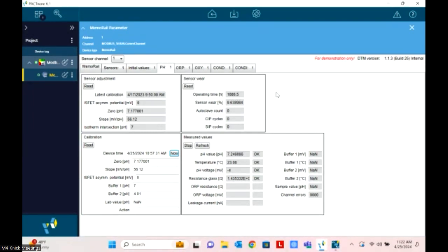Now, obviously, we can start scheduling PMs based off, say, wear percentage. Now we know, as opposed to sending our technicians or our operators out on maybe every 2 weeks or a monthly basis to just check those electrodes and clean and calibrate them, well, why wouldn't we utilize percent wear to give us an insight as to, is it time to clean that sensor and recalibrate that sensor?